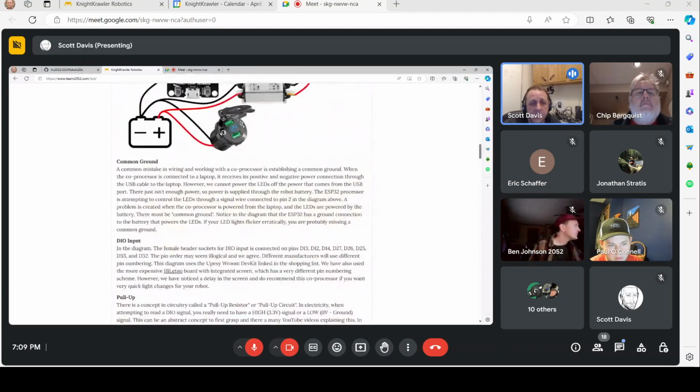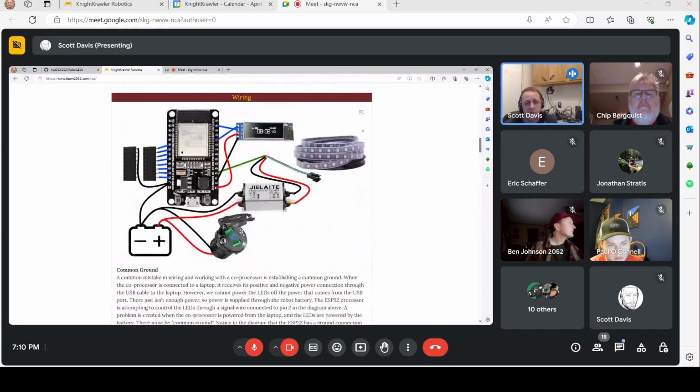Another goal that we had was we wanted to make talking to the RoboRio simple. And what I mean by simple is we want it to be easy to understand for a new programmer or a novice programmer. I think a lot of teams are probably talking between their RoboRio and their Arduino using I2C protocol or an SPI protocol, which are both serial communications. And that's a better, more standardized way to talk between those two chips. But if your processor isn't doing what you think it should do, it can be really tricky to debug if you're not an expert in that system.